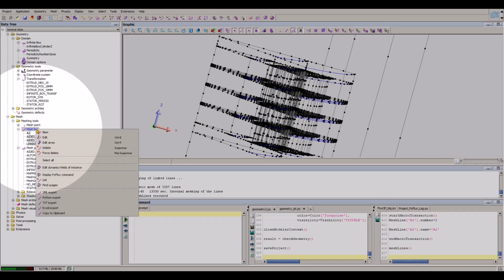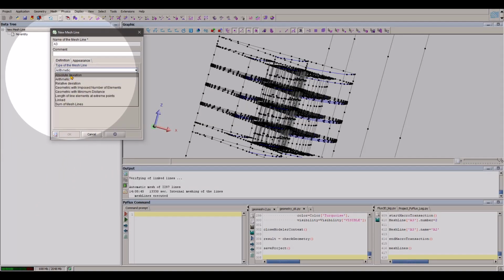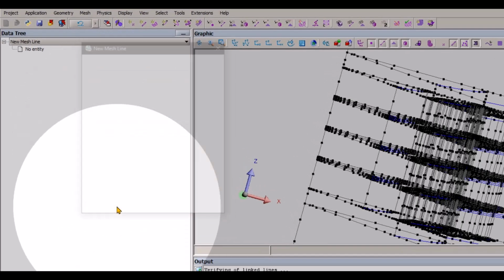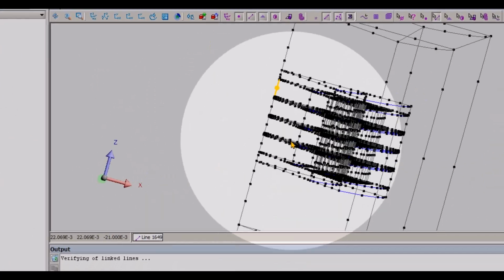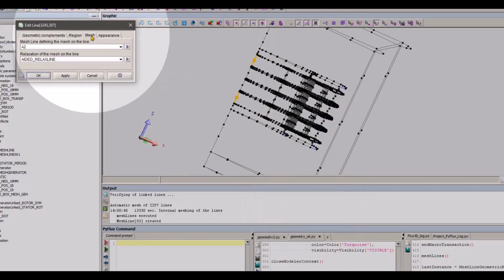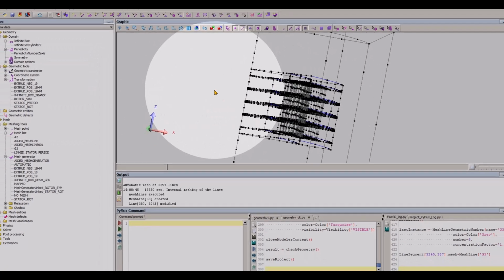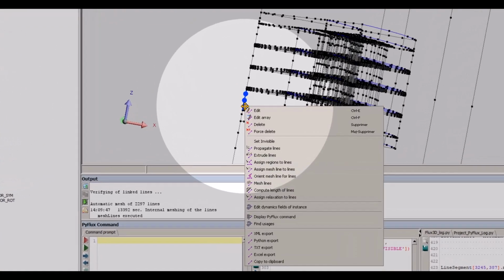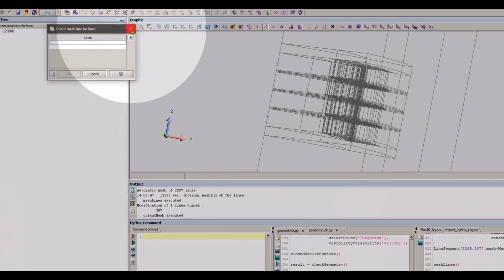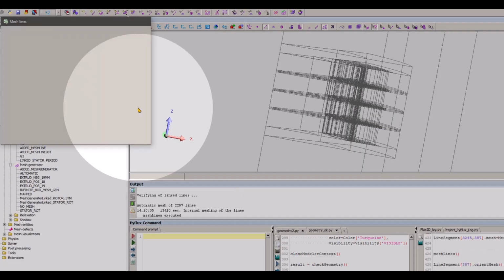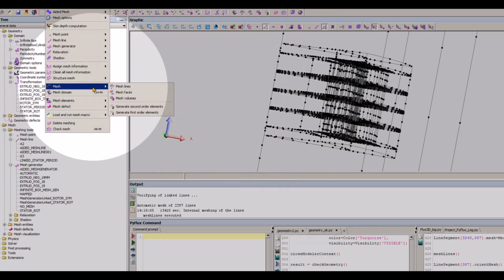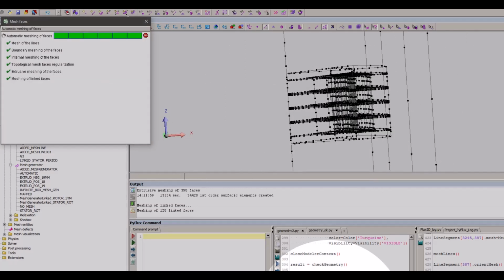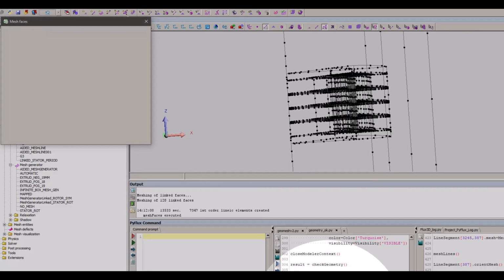Here, as you can see, I moved from 3 elements to 2 elements, but I will modify again the mesh line information on the layer on the border to use a geometric variation instead of the arithmetic one. So then I can mesh, and as you can see, the top is good, but the bottom is not good enough. I will reorient the mesh again. And now when I reorient the mesh, you can see that the geometric mesh is very well assigned.